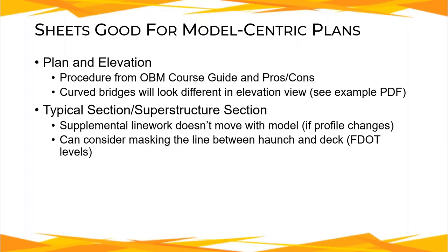One thing you might have to do if you don't want to see those little lines, and it's just a little detail thing, whether you care about that or not, is use a masking element. You have to cover it up with a MicroStation drawn element that has a background color set as the level color, which we do have those specific levels. We've introduced extra ones over the last one or two workspaces ago to help with things like this, where we can mask out things that we don't necessarily want to see. But that's just something else to consider with doing plans from the 3D model.